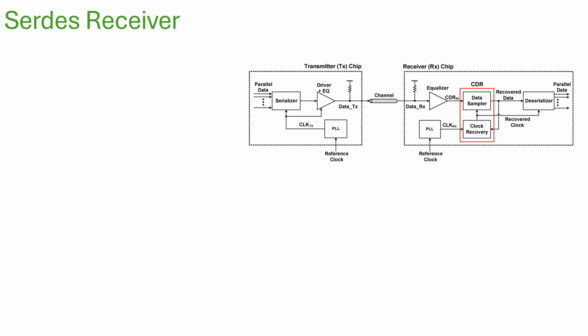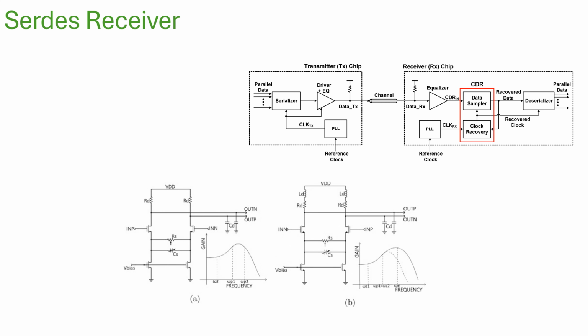Again, let's look into the receiving part of it, the pad connected to the receiver. We expect the signal reaching the pad, or the input part of the SerDes, to be very weak, especially because of the band limited channel. We might need equalization. So generally we start with the equalizer at the first part of the receiver, then we do the remaining part of it, deserialize and later.